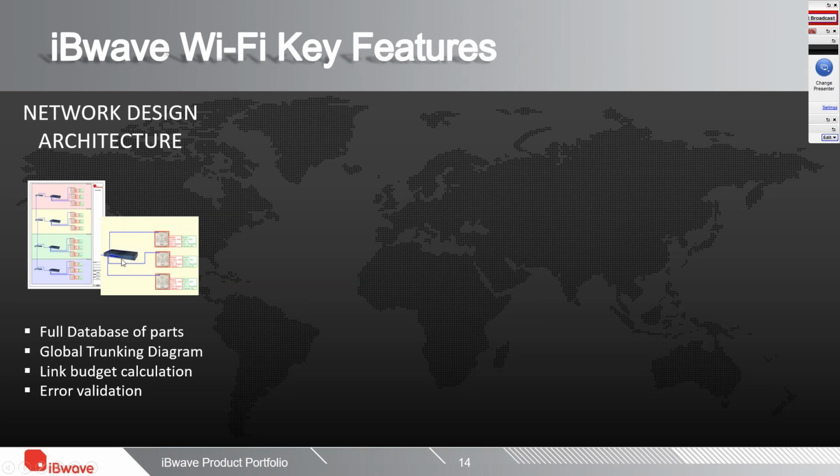Now think of the amount of time that's saved in the commissioning process by having these kind of diagrams that the installer can refer to, or even as an IT technician, I'm responsible for the network in my building, I can see exactly which AP is connected where, and if ever I have a fault, I know exactly which cable to disconnect or replace or troubleshoot and so on. So this is a huge time saver, not just at the design process, but later on.